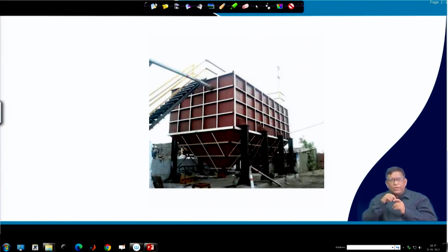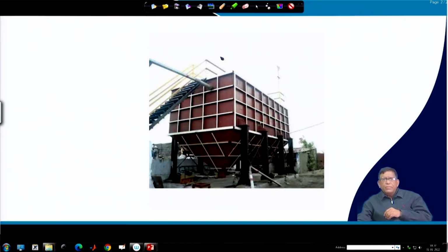Now, as I told you the other day, there is a problem of flow, that means arc formation, or rat holing and all that may happen at these portions. Here you may have rat holing or an arc or bridging, and then the material will not flow. So, in that type of situation, just the bunker alone will not do. You will have to use some flow aid inside.